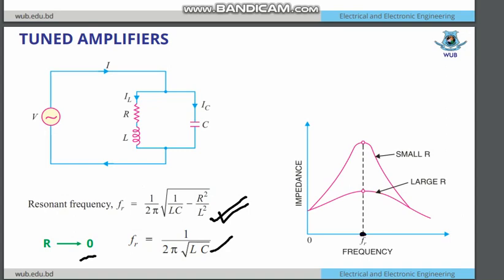As far as the resonance frequency, whenever the resistance R is smaller, the response increases to the peak point. At this point the R is smaller. If R is equal to 0, you will get to the top of the peak. That means the maximum current will go through the circuit if there is no R. So the circuit will be like that, and the selectivity will be high.